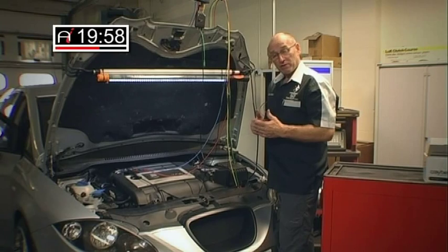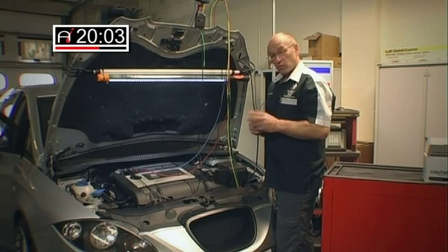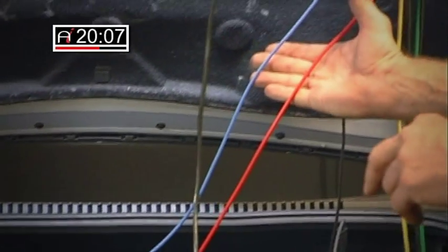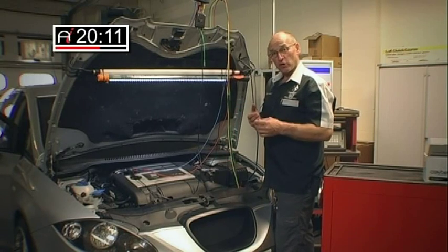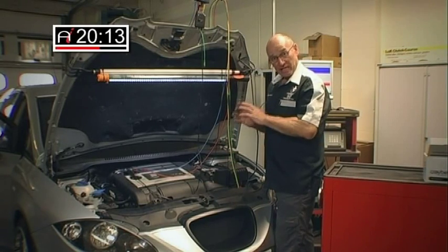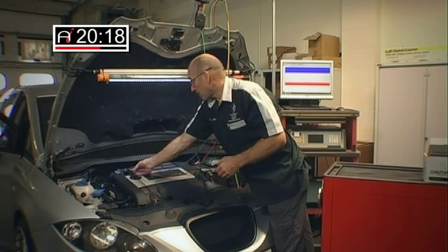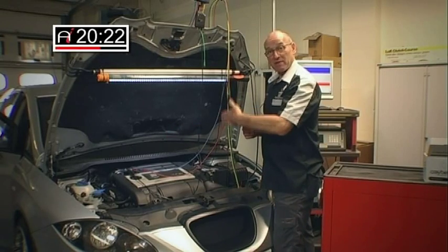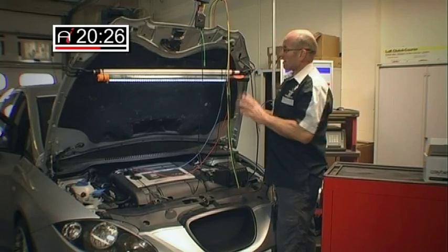The actual output signal frequency has been connected with two channels, channel A blue, channel B in red, on the same pin, because I want to show one as a frequency and show one as a conversion, which I'm going to show you the actual setup for. That connection is in the third pin of the air mass meter, closest to the engine intake. So in other words, the pin nearest the engine intake is the output signal. That said,